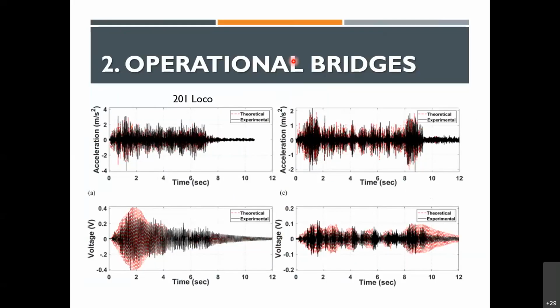So now think of any standard electrodynamic shaker in a lab. They typically go between, say, 0 and 200 hertz, but at 200 it heats up a lot. But somewhere within these frequencies that we are looking into, the typical amplitude and the acceleration can all be exactly recreated.